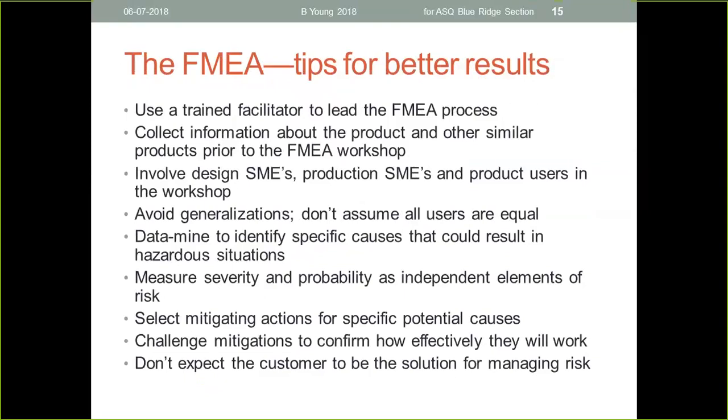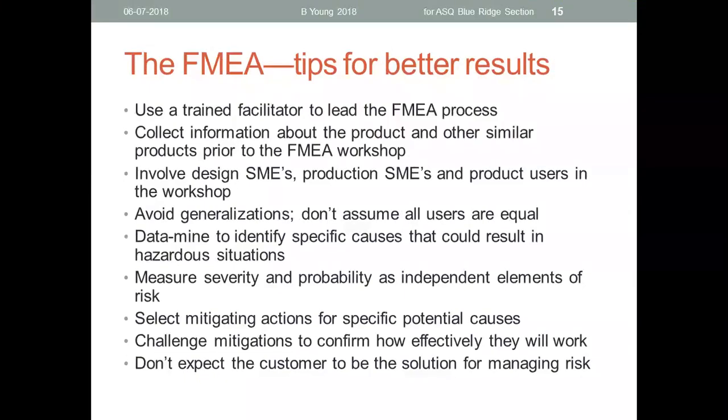There's lots of tips for doing FMEAs that I've heard from different sources. These are the ones that I find to be very helpful from my own experience. Having a trained facilitator really facilitates that whole process when you're doing an FMEA. It's a complicated process, and people can get off track, especially if this is not something that they do frequently. So having somebody leading the discussion can really economize on your time and your effort.